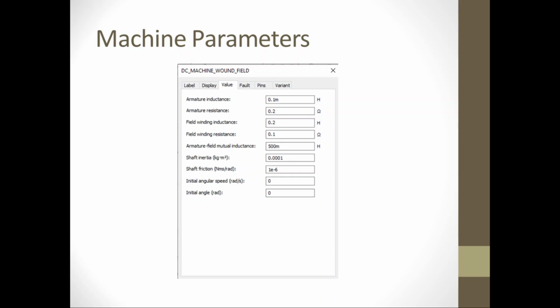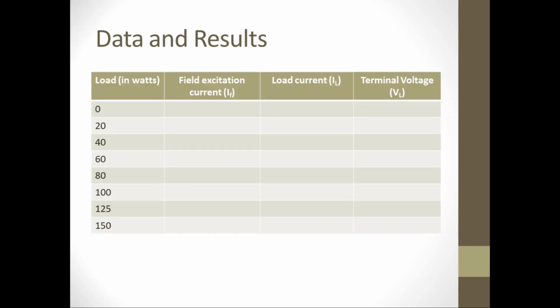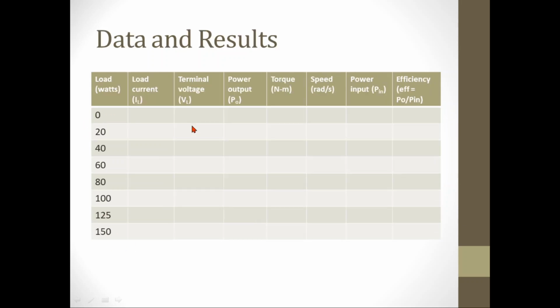So we are asked to fill in the following data: the field excitation current, the load current, the terminal voltage, with respect to the different wattage of the load. At the same time, we also calculate the following data in the second table.